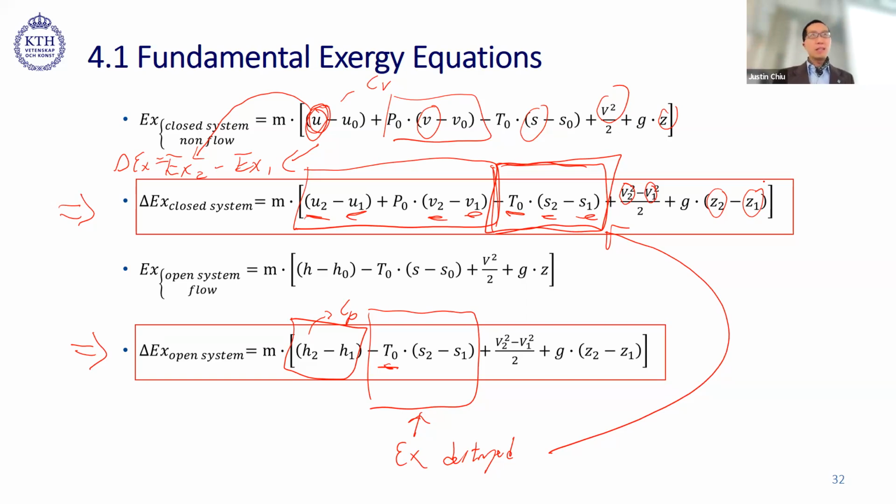Yes, please. And the other V is then volume. So this one is exactly. So here it's specific volume because I have my mass in the front. So basically it's the volume divided by mass. That's why I have the squiggly V. And everything here is specific, so specific internal energy, because I have my mass in the front, a specific entropy, and then the big V, it is direct velocity, because we need to have mv squared divided by 2. And then also the height potential, this is the mg delta z. So it's in meter for the zeta here.